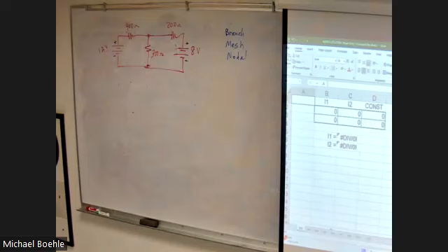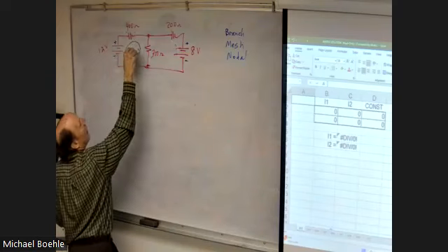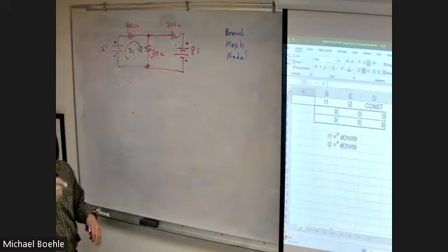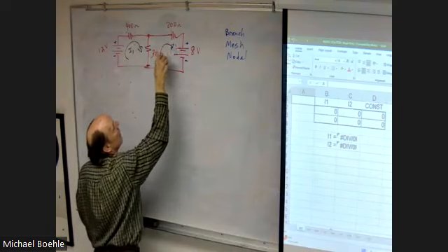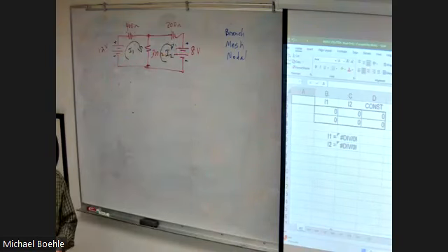All right. So I'm going to draw my circulating currents. This is where I'm going to start to guess wrong. I always draw my currents clockwise. 1, 2. So how many equations do I need? For 2 unknowns, how many equations do I need to come up with? 2. Well, that makes it nice, right? Because I already know how to draw 2 equations because I have 2 loops to go around. Here's the tricky part, or here's the part that is just a little bit different. All right, you'll see it here in a second.